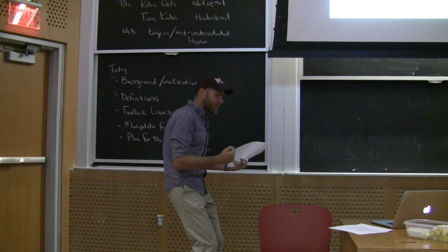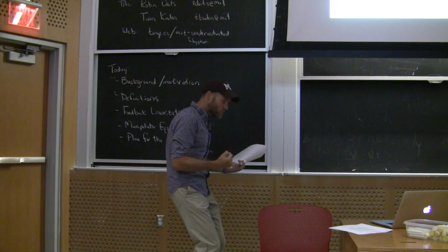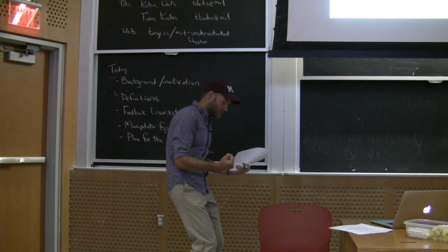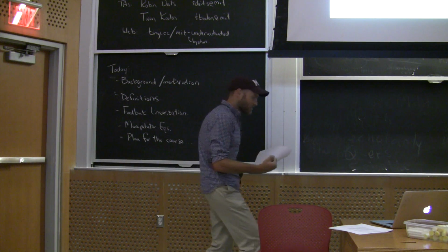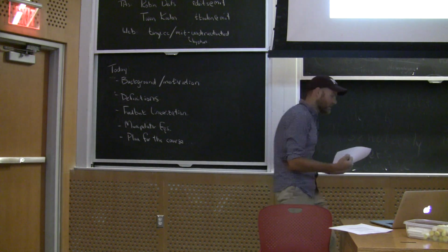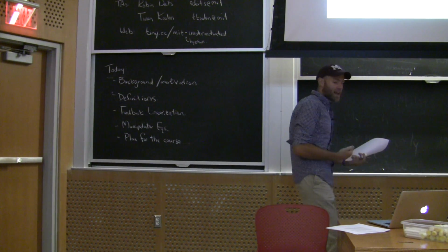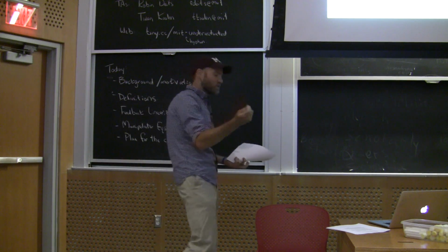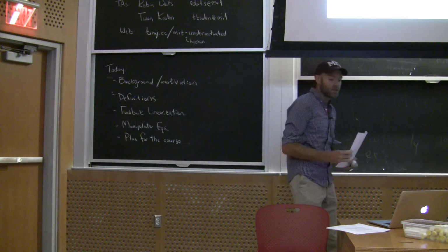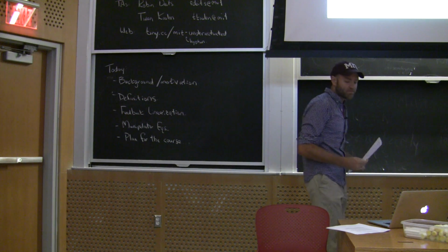But Asimo is also doing more than that. It's actually using very high gain feedback to effectively cancel out the dynamics of its legs when it's walking around. So in some way you could say that Asimo is walking like a robotic arm that you might use on an assembly room floor, and really not walking like a human.